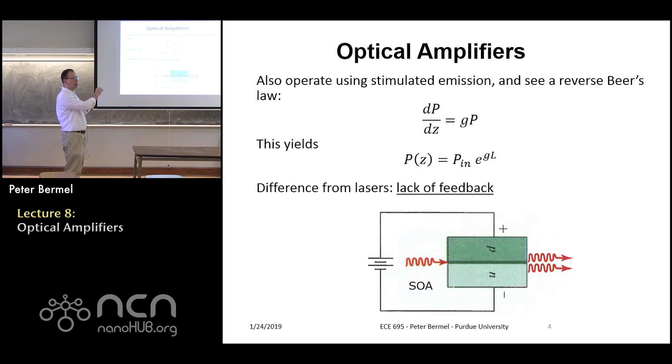So you'll have a gradual decay as you travel down the fiber, and then you'll have a boost, and then you'll have a gradual decay. But the overall pattern will be basically periodic over all these links. And so you can just keep it going as long as you want, right? So that's really the most critical concept.